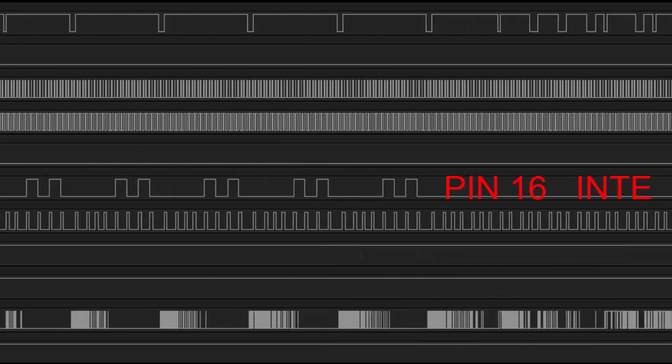Let me zoom in to a reset. Okay, so here's my reset. The line we're interested in is this one down here. We can see that this is our reset, and as soon as it resets, you can see my 5 toggles of the interrupt enabled output line. I have it at 0, and I go high, low, and then repeat that with a counter and a jump instruction 5 times. That's why the timing looks a little funny. I go high, low, and then there's a period while it's doing the loop, and then high, low, and it repeats that 5 times.